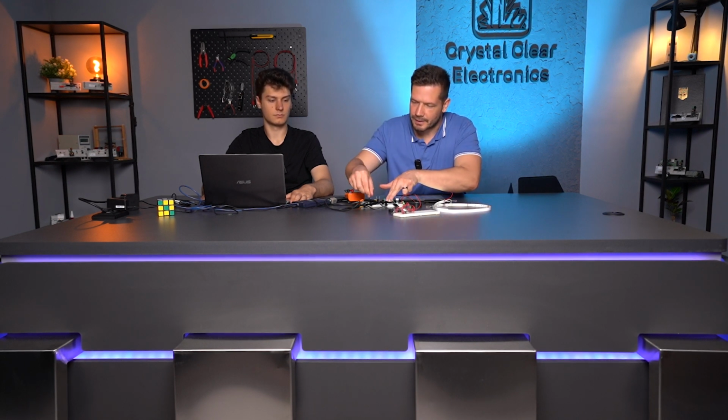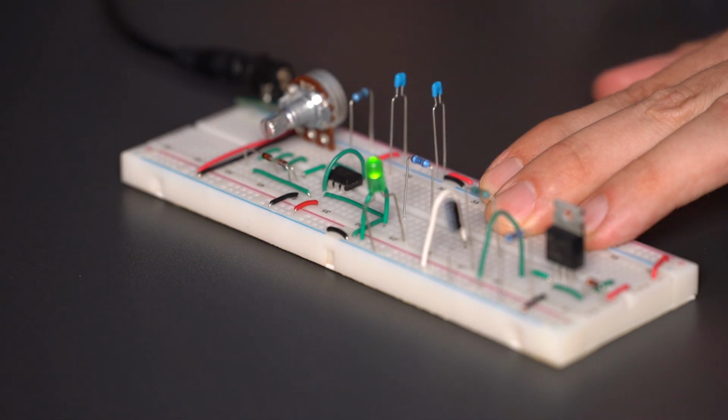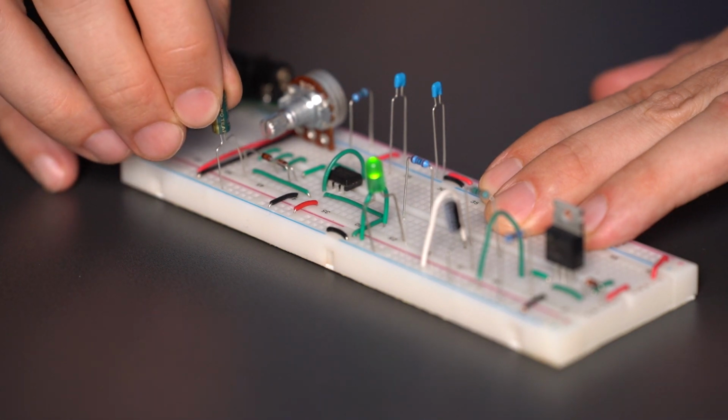If you are curious about the blinking, replace the C1 capacitor with a higher value. We have seen this earlier, but we will show you one more time. If I place a higher value capacitor at the exact point, then we can see the blinking of the LED with our eyes.